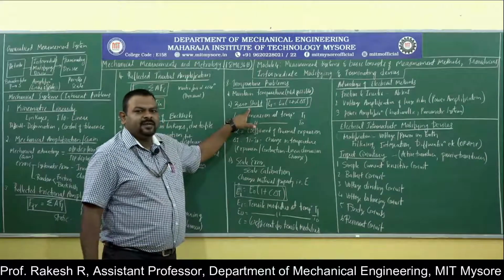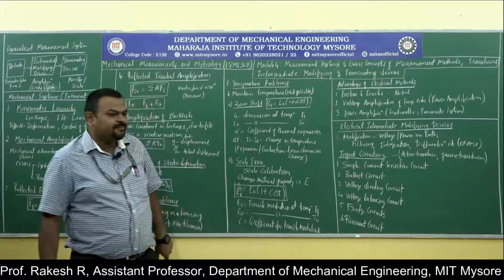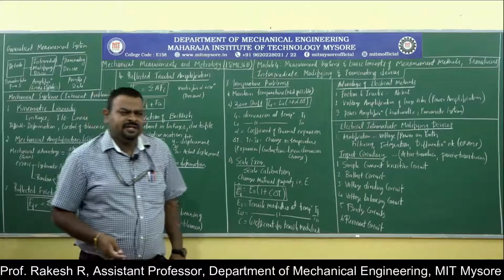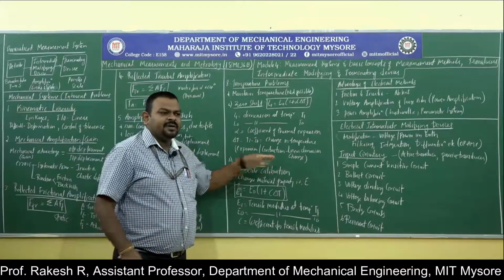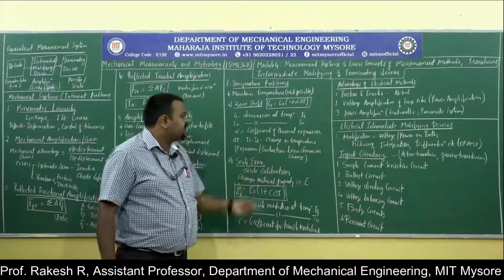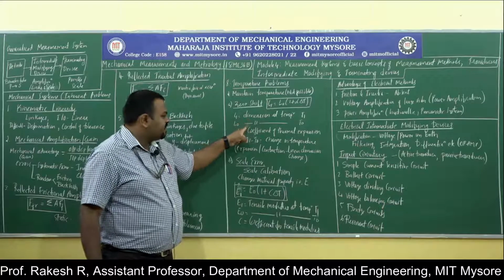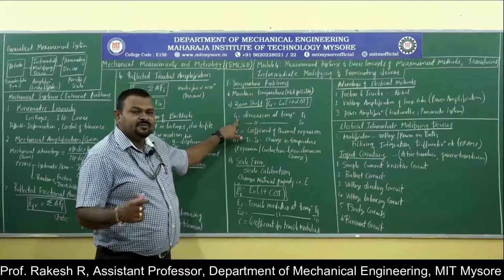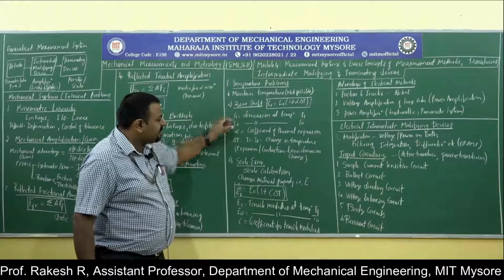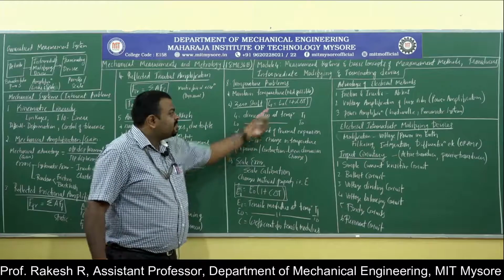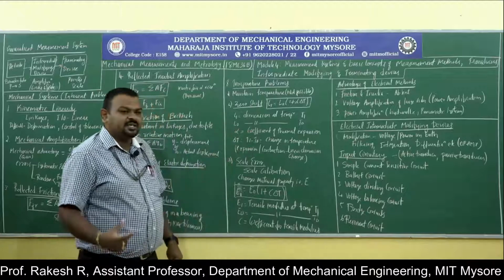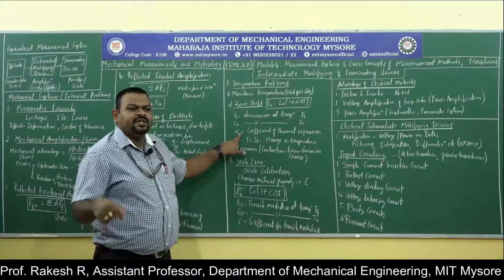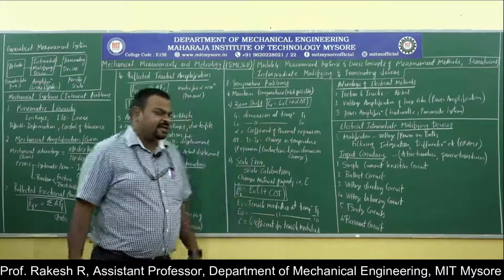There are two problems in temperatures. One is zero shift, another one is scale error. Zero shift is nothing but contraction and expansion, as I already explained with the steel railway track. Because of this, the linear dimension will change. L1 is the dimension at temperature T1, and L0 is the dimension at temperature T0. What is the change of dimension? L1 minus L0 is the change of dimension. That results from the change in temperature, and how much it changes corresponds to the coefficient of thermal expansion. Again, this is a material property, and the coefficient of thermal expansion is different for different materials.